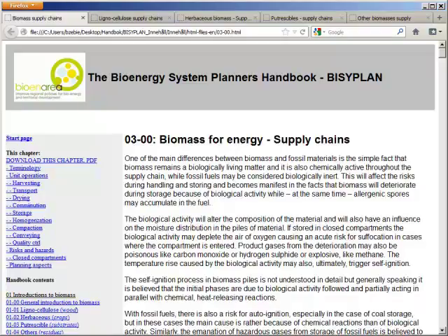For the product fuels resulting from any type of conversion, be it thermochemical conversion or be it biochemical conversion or pyrolysis, the storage situation is different. Whether a gas is produced in a thermochemical process or via a biochemical process, then the product gas will contain the main part of the chlorine content of the fuel, and that chlorine will be present in the form of hydrochloric acid, basically in gas form.